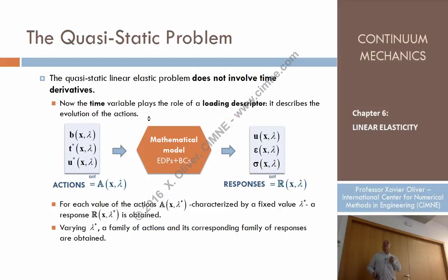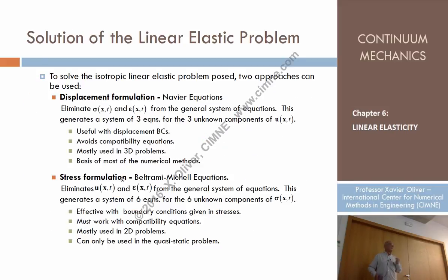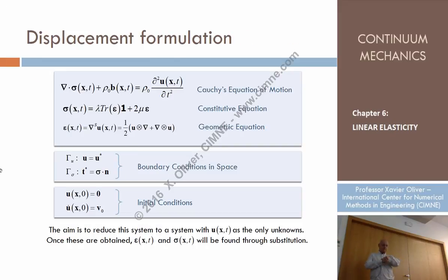And the other alternative is to use the so-called stress formulation. This is, I would say, nowadays just educational. Educational because it's a way to show you how engineers have traditionally used some smart solutions to solve complex problems, as the elasticity problems were. Nowadays, with the numerical methods, I just anticipate that the method that is used 99% of the times is the displacement formulation. Anyway, we are going to examine both of them.